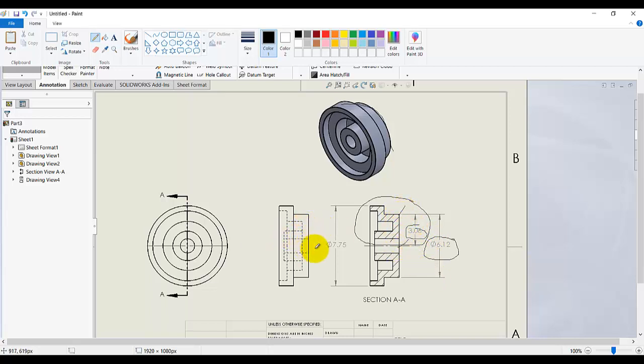And this is the right side view. This half portion we draw on our right plane, and then we revolve it. So that is the whole concept of the revolve command. You have to try my previous tutorial, and there is another tutorial related to the revolve command, in which, the same way, we needed to draw the half sketch from the right side view. We design a half sketch, and then we use the revolve command. This is the concept of the revolve command. So you must understand it: for the revolve command, we draw the half portion of the sketch in SolidWorks.